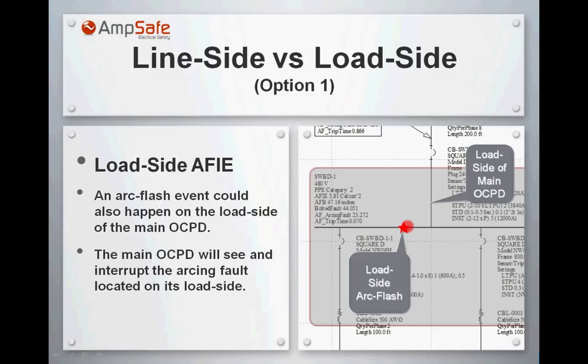So that would be the case if you have an arc flash in any section of the switchboard after the incoming section, correct? So you have an arc flash here or here or here or any other section. You will be able to count on this breaker to open. Therefore, the incident energy here might be 5.81 calories per centimeter squared instead of 44.